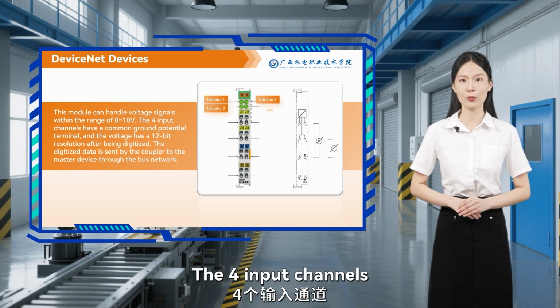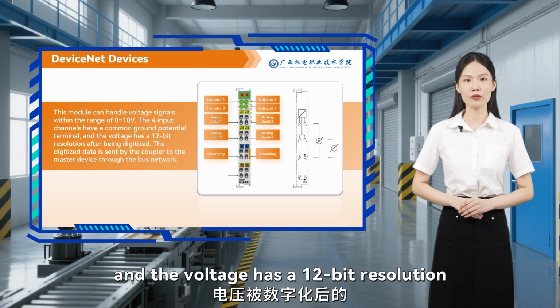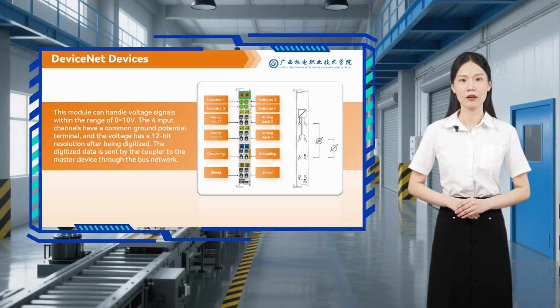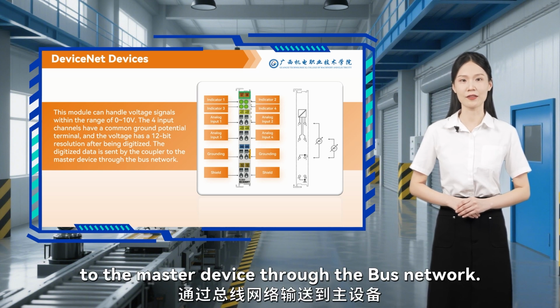The 4 input channels have a common ground potential terminal, and the voltage has a 12-bit resolution. After being digitized, the digital state is sent by the coupler to the master device through the bus network.